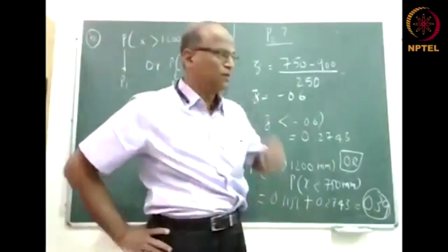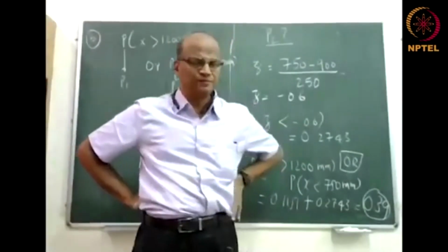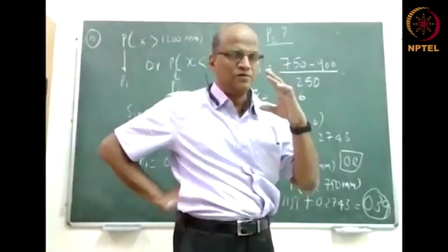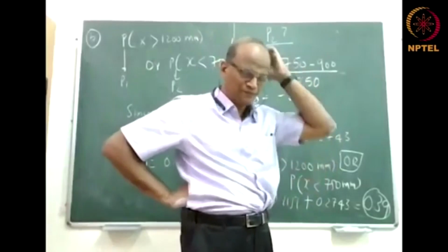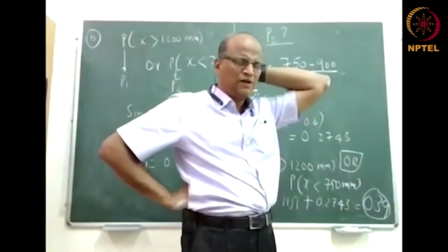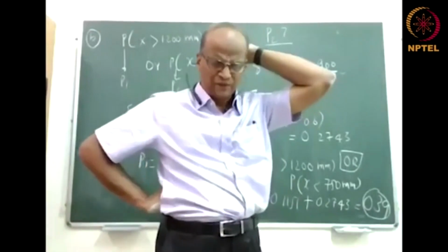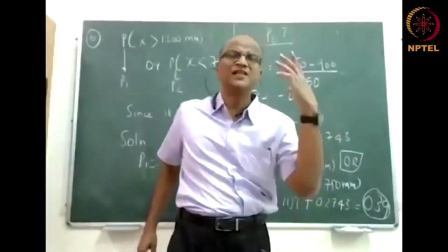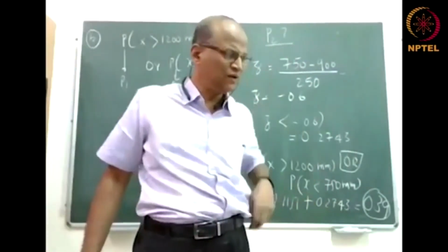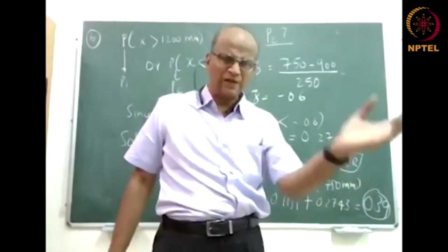Okay, so we can say that sigma is 250 and the mean is 900. So 3 sigma is 750. Watch my arguments very carefully. Mean is 900, sigma is 250, so 3 sigma is 750. So 900 plus 750 is 1650. If you work out the probability of the rainfall exceeding 1650, what should you get? 0.03% or something. 0.15%, whatever.